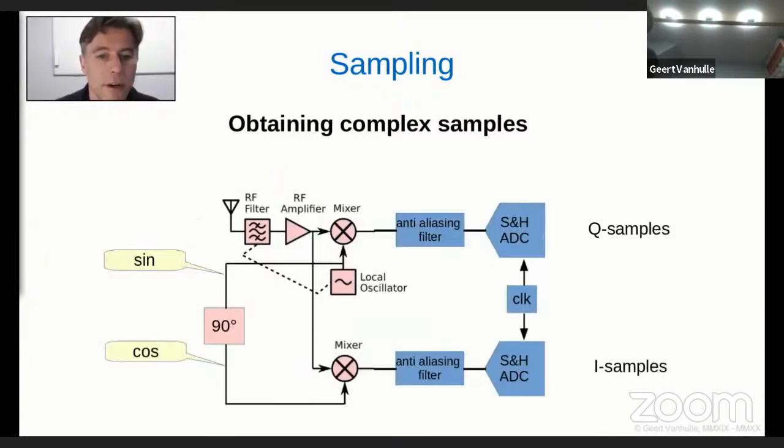Well, this is the circuit. We start with a local oscillator, and the RF signal goes into a mixer. The output of this mixer, as we have seen, is the cosine wave. And we shift the local oscillator by 90 degrees, which produces a wave of exactly the same frequency and exactly the same timing, but with a 90-degree shift.